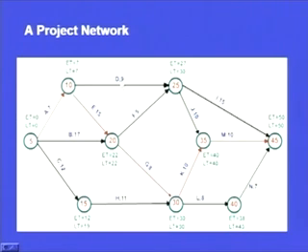Now when we go to activity D, when can it start at the earliest? It can start at the earliest at the end of 7 days. So it can start after 7 days. Similarly, activity E can also start after 7 days, and activity H will start only when C is completed, and C is taking 12 days. So activity H will start only after the completion of 12 days. So earliest start for H is 12, earliest start for E is 7, and earliest start for D is also 7. In this way we see that we can construct a network diagram.